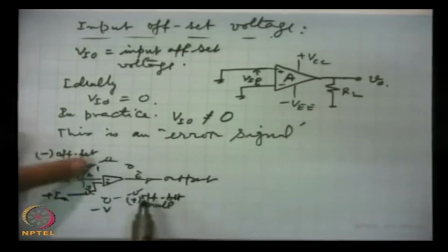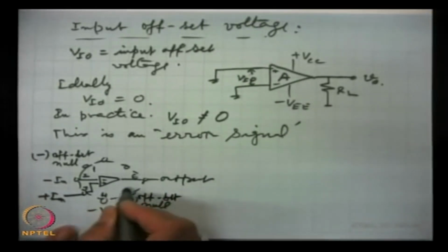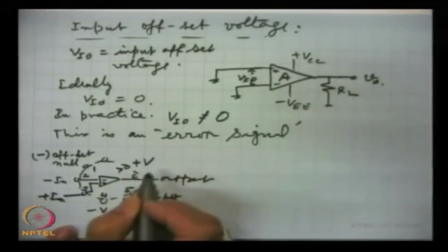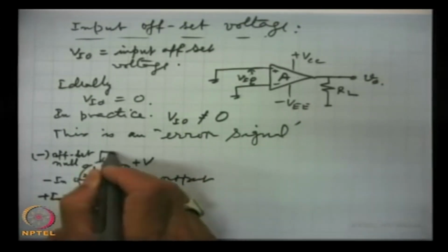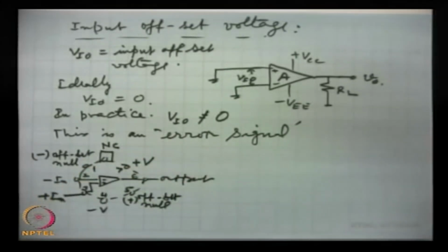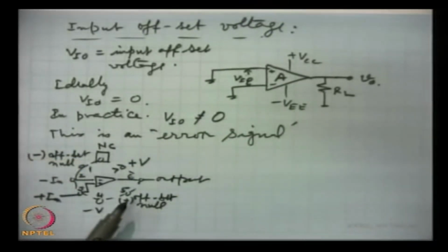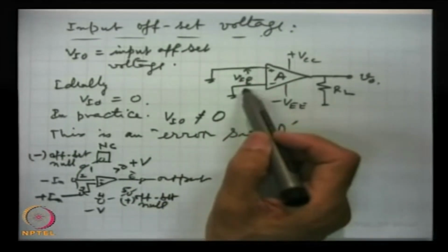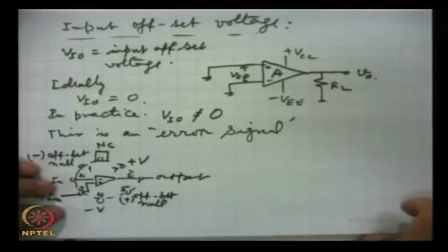So, between these two, 1 and this is terminal number 4, this is 5, this is 7, which is plus volts, that means for plus VCC, and this is the extra terminal which remains normally closed, NC. So, an offset voltage equal in magnitude and opposite in phase of what is existing here is applied between these two, and how we do that? Let us look here.